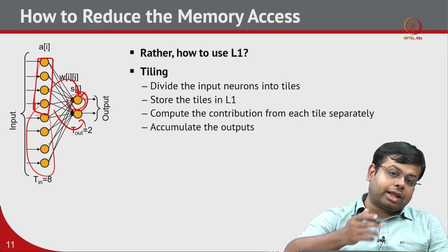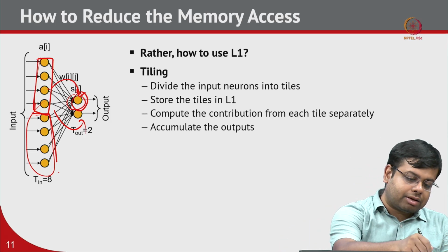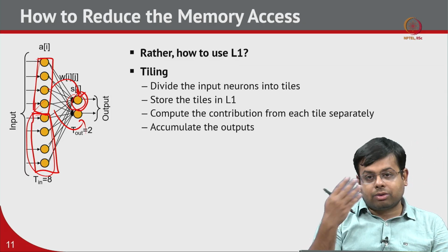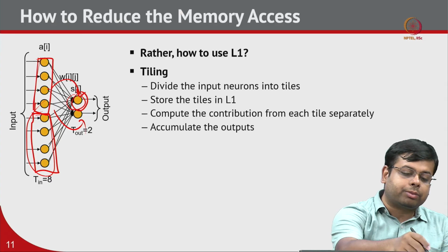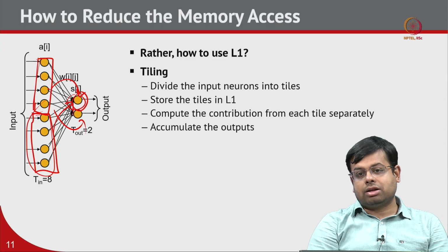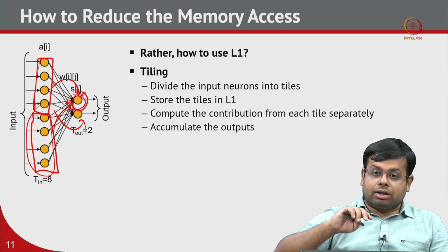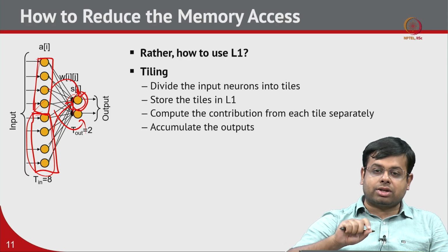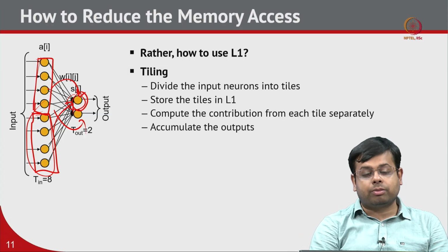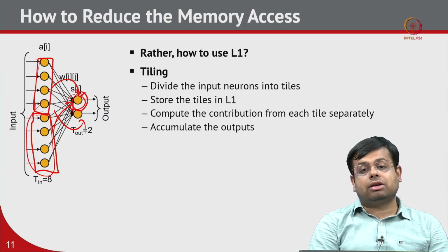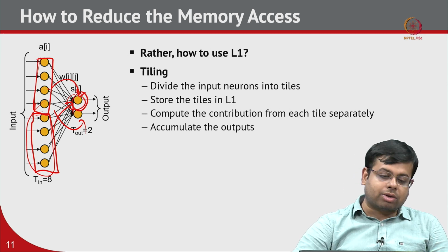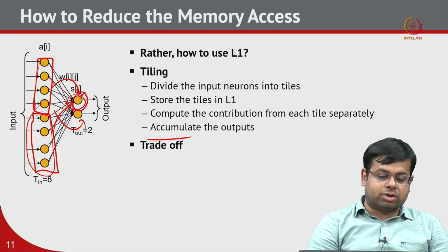Whenever the next tile comes into the L1, again we have to compute its contribution to S0 and S1. Whenever we compute that contribution, we have to add it to the previously computed, or partially computed, S0 and S1. That is why we need to accumulate the outputs.